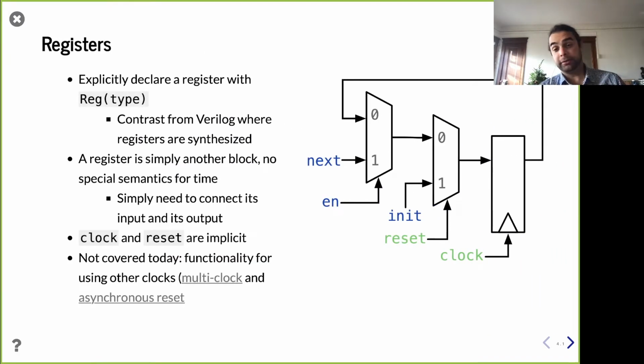First off, let's talk about registers. Now, of course, a register, remember on the right, that's this box over here, the triangle, right? This triangle tells us a positive edge-triggered flip-flop. In other words, once per clock cycle, we'll take the input, and that becomes the output. And for the remainder of that cycle, I can change this input however I want, but the output won't change until the next clock cycle, in which case it changes again, right? So this register here is going to hold the state.